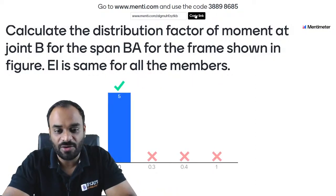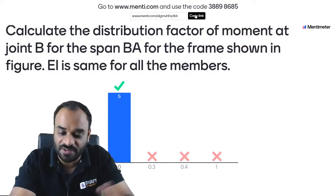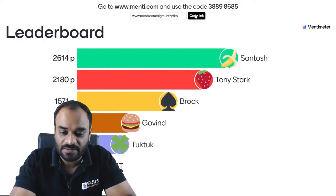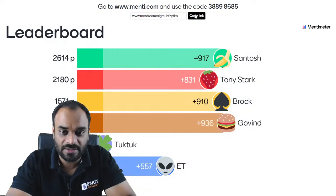Very nice. All of you have given the correct answer, 0, because the far end is free. If far end is free, stiffness is 0. If stiffness is 0, distribution factor is 0. Very nice. So let's see who has given the answer correctly and quickly.